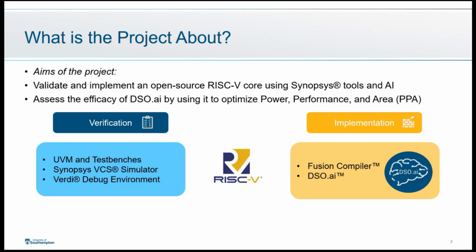For this, the project was split into two parts, verification and implementation. For verification, we worked on the Bluespec RISC-V MCU with RTL and UVM test benches provided by Synopsys. And this aimed at giving us hands-on experience with industry standard verification flows. That's something that's not usually covered in university courses. And for implementation, we used Fusion Compiler to implement the same RISC-V core, and then used DSO.ai to get better power, performance and area results.